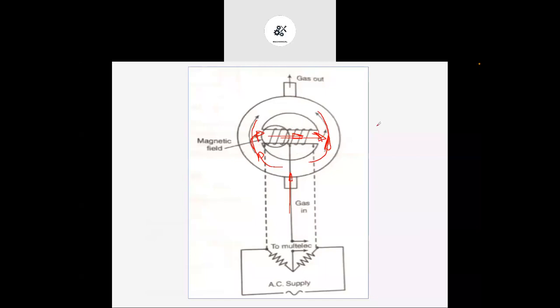Okay, as the temperature of this winding decreases, its resistance is also going to decrease. Because the heat will be absorbed by the oxygen, its resistance will decrease, and that will cause the variation of the resistance inside the Wheatstone bridge, or the unbalance in the Wheatstone bridge circuit. That unbalanced resistance is used to measure the quantity of oxygen inside that particular flue gas.